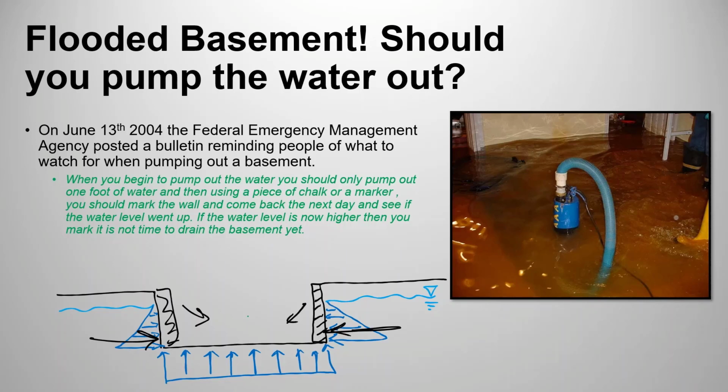That's why it's recommended not to pump the water out of your basement and to let the water level outside of the basement go down. Once the water level is down and down and down, then you can slowly pump the water out of your basement. See, you can use all of these principles that you're learning in fluid mechanics and also in other courses to think about simple daily problems that you experience every day. And that's the cool thing about fluid mechanics.